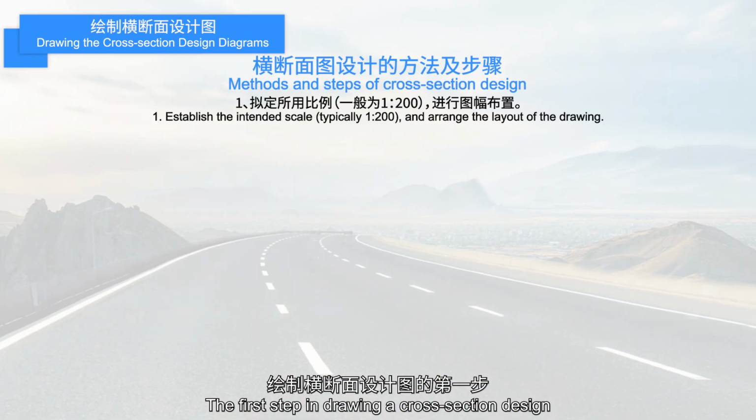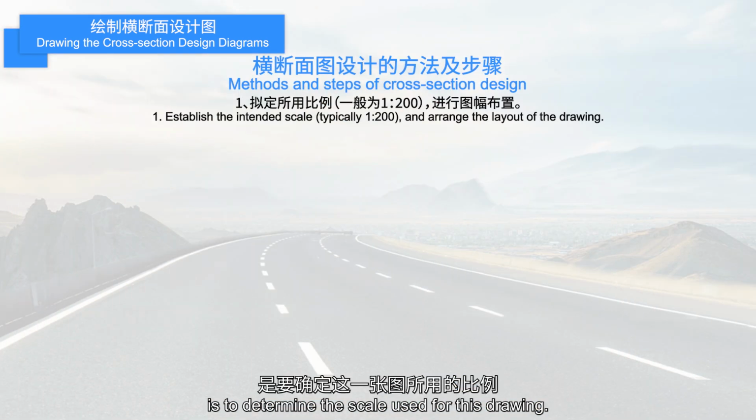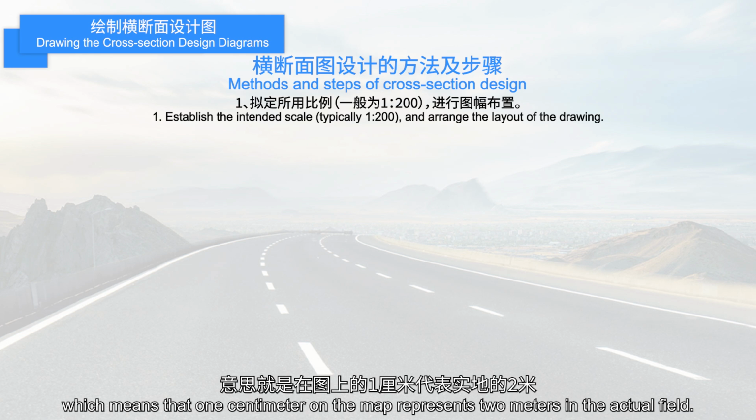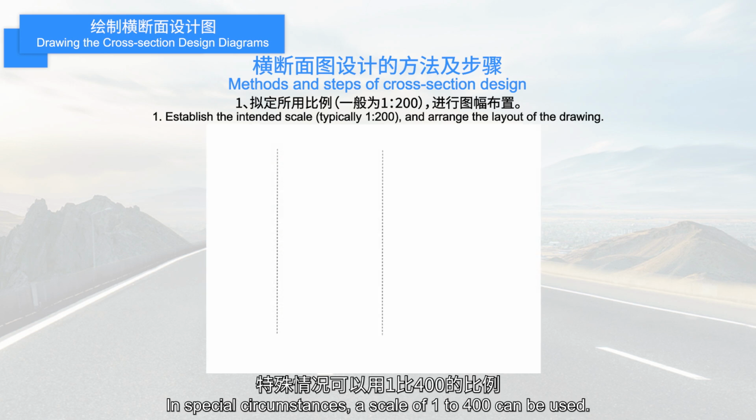The first step in drawing a cross-section design is to determine the scale used for this drawing. The commonly used scale is 1 to 200, which means that 1 centimeter on the map represents 2 meters in the actual field. In special circumstances, a scale of 1 to 400 can be used.